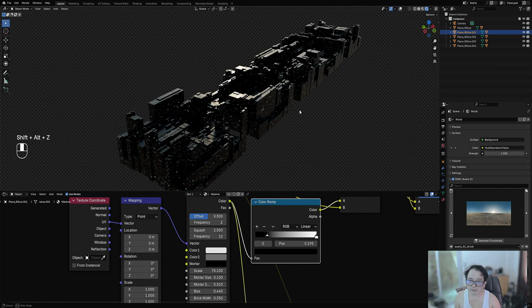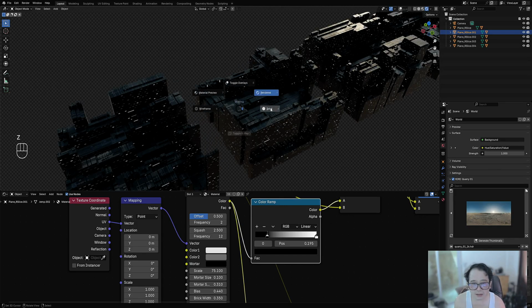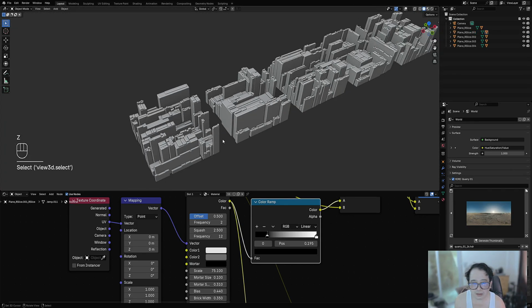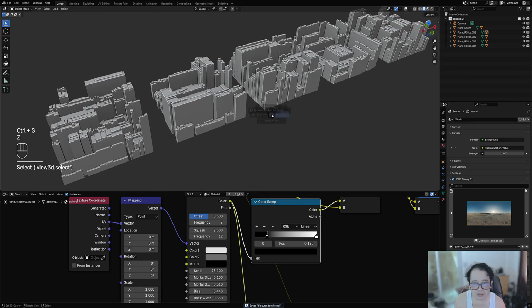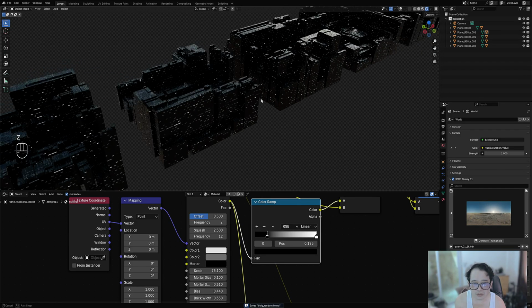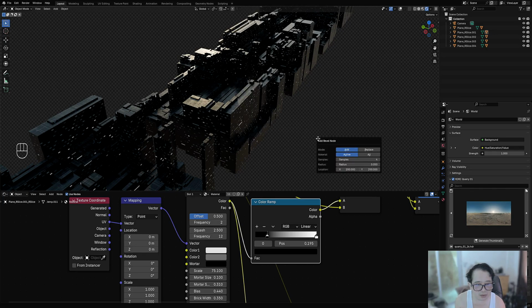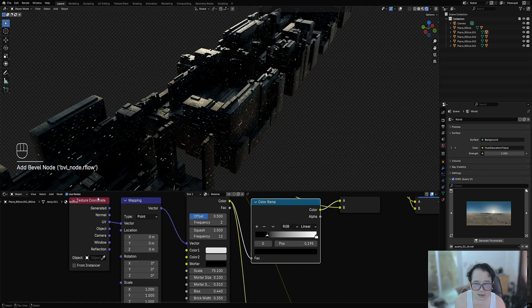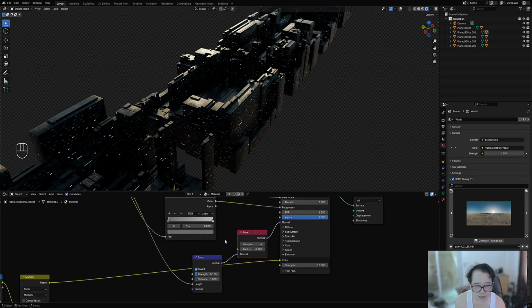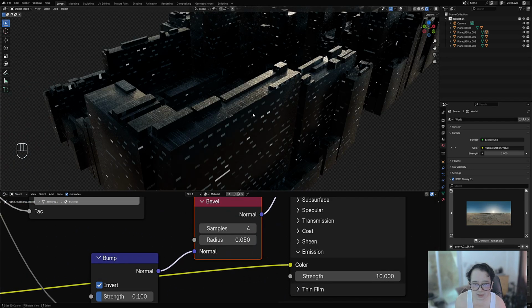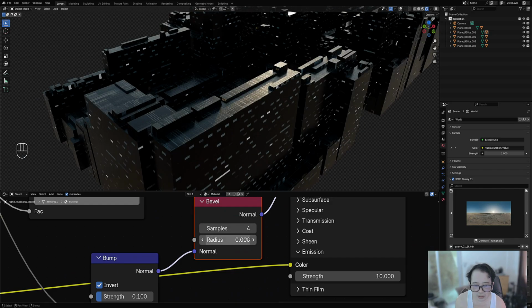All right. And go to the shader. I'm going to save this. And let's just introduce a bit of bevel. Just a small bevel. Extras, shading, and a bevel node. And let's just fix the radius because it's too much. 0.0001. Okay. 0.005.